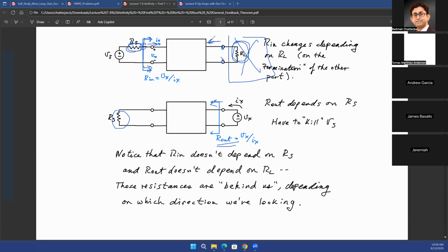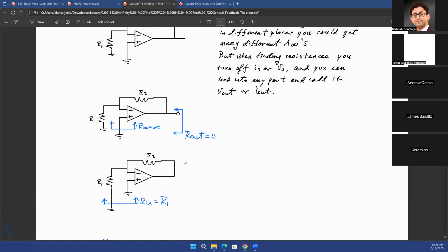All right. So with that in mind, maybe we can take a look at a few examples. Some of these examples are very similar, very easy to understand, and you have looked at some of these circuits in your 3111. So for example, this particular circuit over here, if you connect, let's say, a voltage source at this point, right? So this is your inverting amplifier, right? You have an R1 resistance connected to the inverting terminal of the op-amp. You have a feedback going on from the output terminal to the inverting terminal of the op-amp. And the non-inverting terminal is connected to an AC ground.